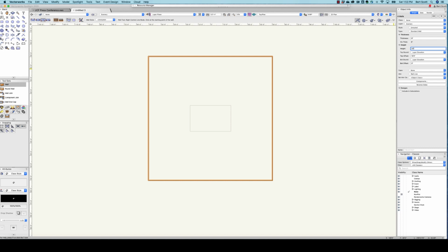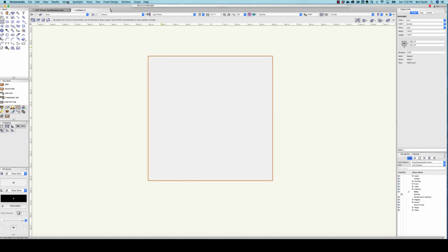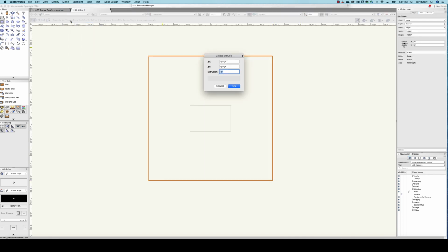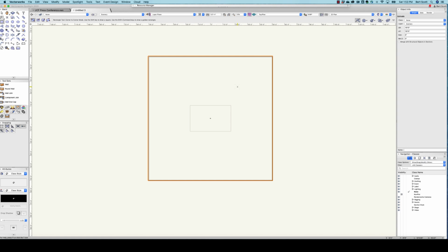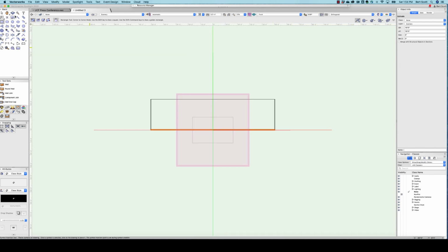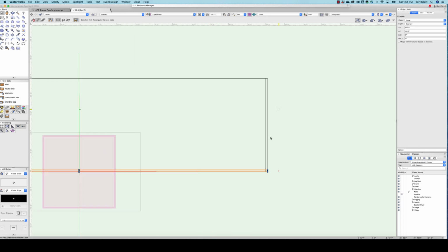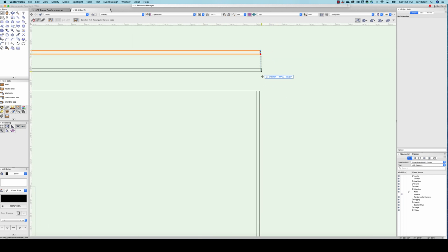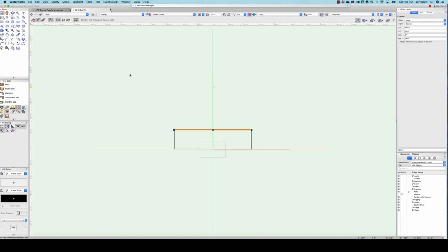A room this size, a 100-foot square room, is going to have tall walls. And then finally, we want to draw a ceiling. So we'll draw another rectangle here and do an extrude. We can extrude that 6 inches and then go to front and grab the ceiling and put it on top. There's our room.